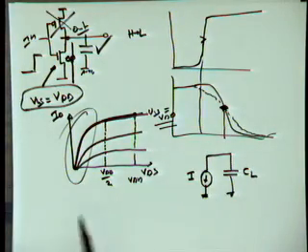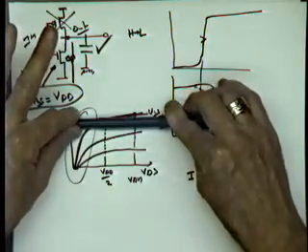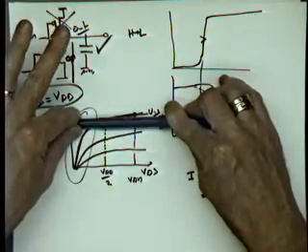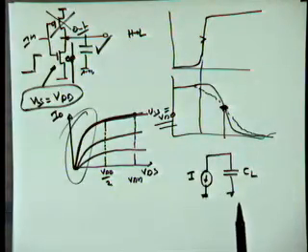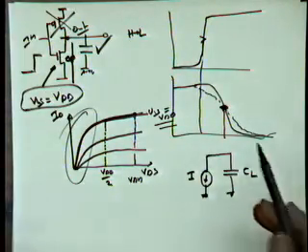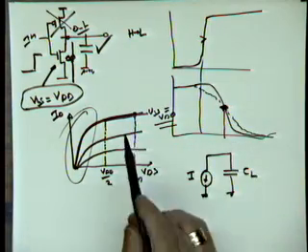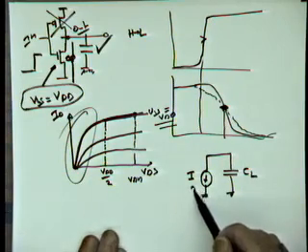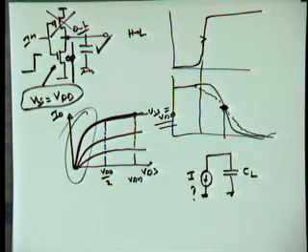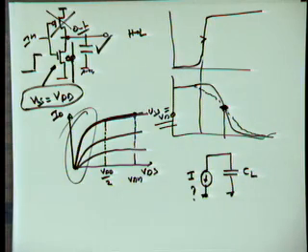Now, life would be really beautiful if the current would be really flat during this period of time. Then I wouldn't even have to worry, the current would always be constant and exactly equal to this I. In reality, there's some channel length modulation effect. Actually, you see this curve goes upwards a bit. So the question is, what do I use for I? I want to replace it by one constant current over the whole interval of interest.